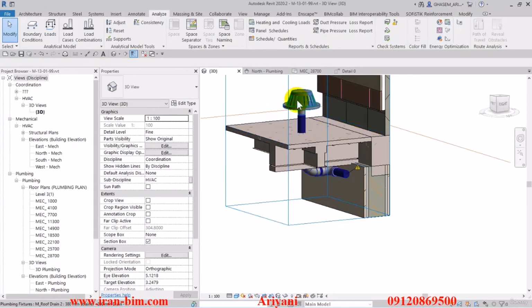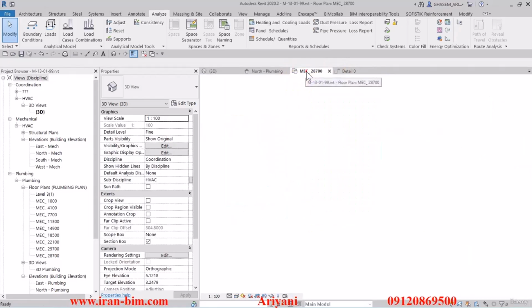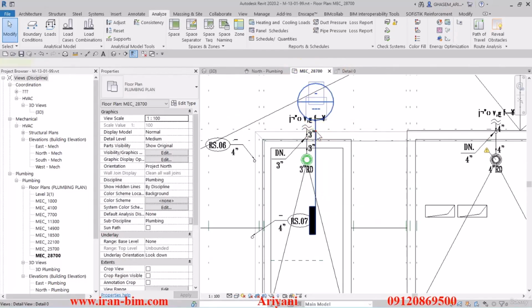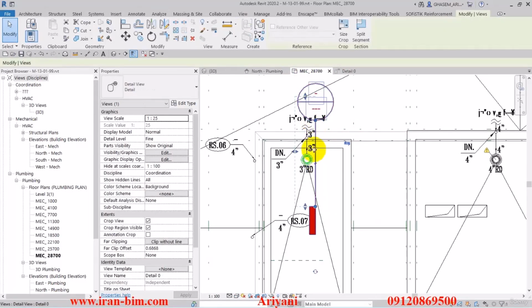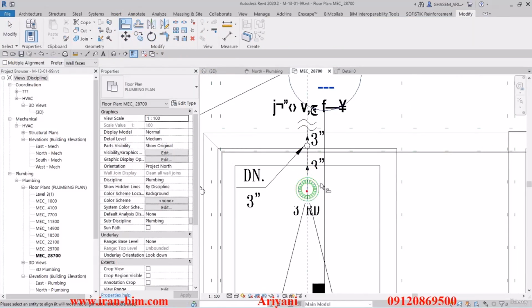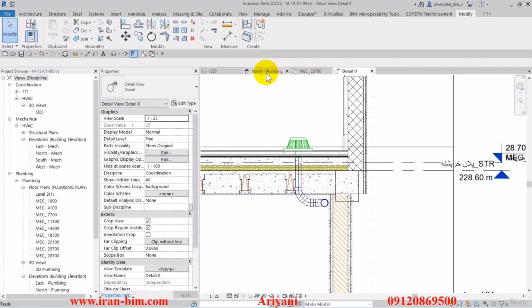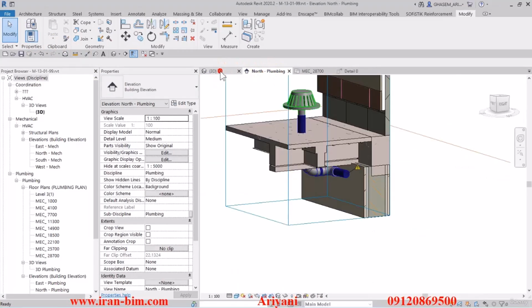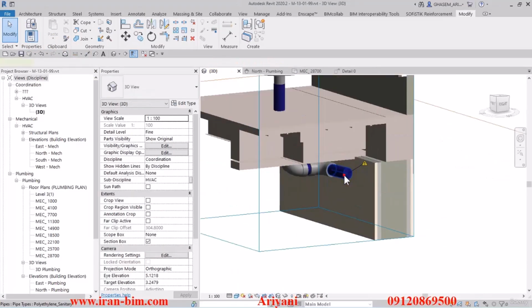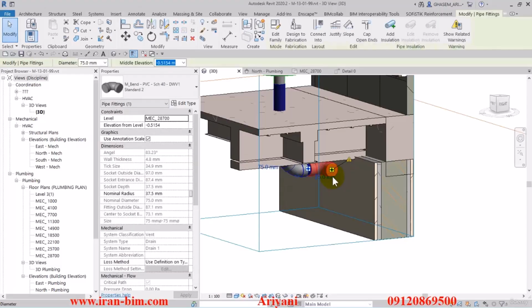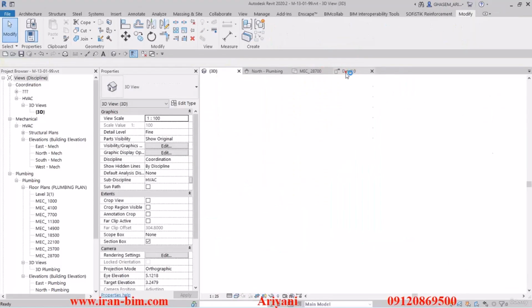And the reasoning for it is that whenever you make a cut in the plan and then you try to draw inside of it, the cut line itself becomes our work surface. So just like this piece right here, you can come over here and put the cut line right in the center of this so that you won't encounter this issue again. So going back to our original plan, I'll delete the piping bit and I'll also delete this bit as well.